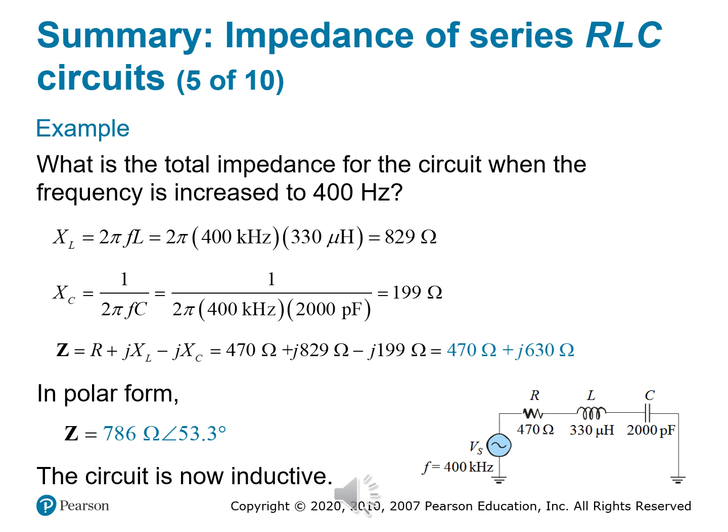What does this all mean? It means our circuit has flipped from capacitive to inductive, and think of it this way. Earlier at 100 kilohertz, the capacitor was dominating the dance floor, but at 400 kilohertz, the inductor has taken over, spinning with higher reactance. The phase angle is now positive, telling us that the current is lagging the voltage. So we have a classic sign of inductive behavior.